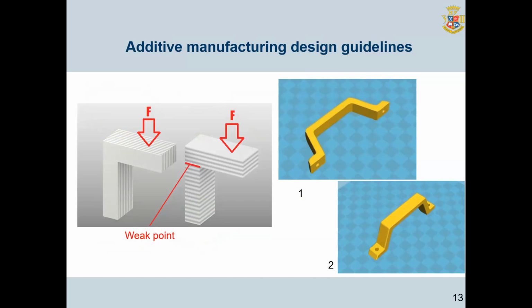How to place the model on the desktop depends on its strengths. The load must be distributed across the print layer and not along. Otherwise, the layers may disperse. To make it clear, let's look at two L-shaped models. The lines show the layers of print.